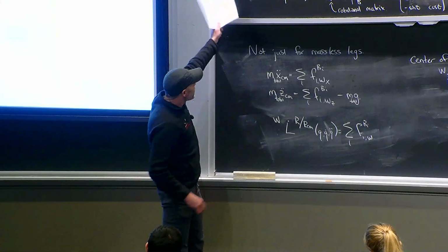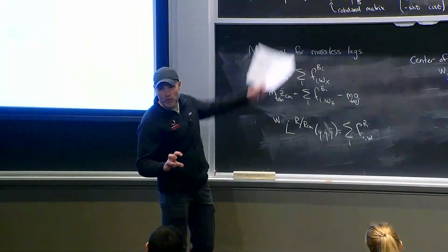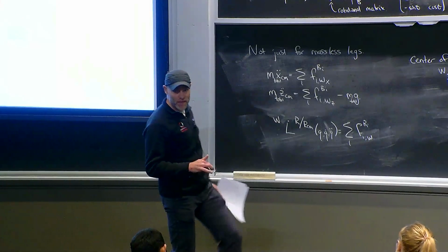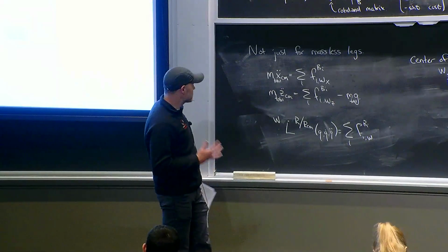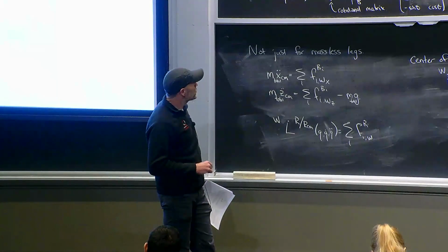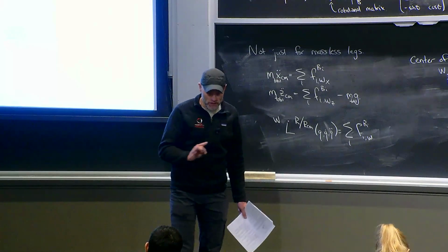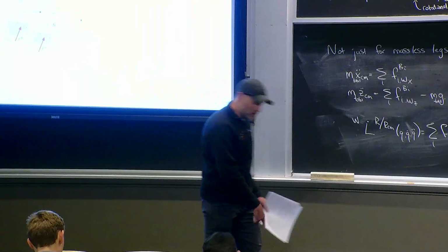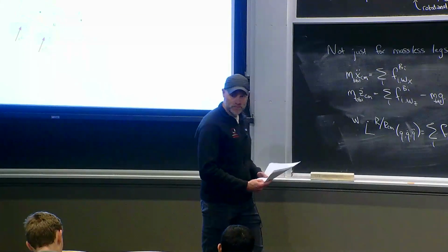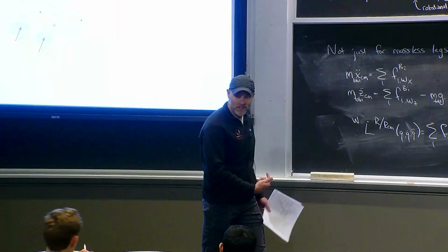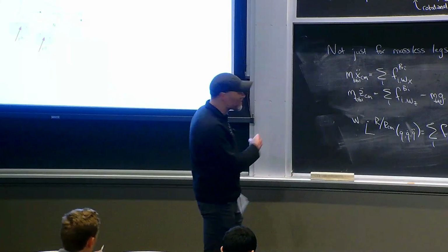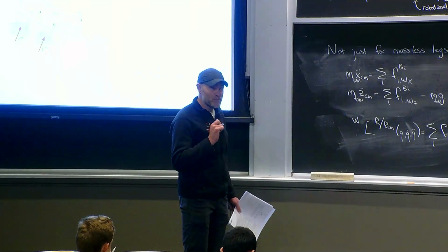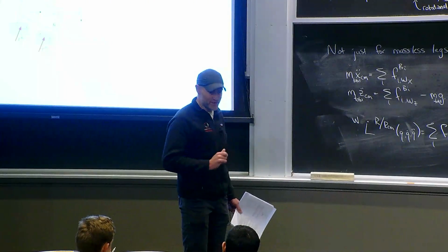Now, otherwise I have these dynamics, and I have a bunch of constraints on when F can be non-zero. When I'm touching the ground, I can push. When I'm not touching the ground, I can't push. That's the essence of the problem. There's one other thing we left out. In the walking robot, in the compass case, we talked a lot about the impulsive collisions. We said that there was energy lost every time your foot hit the ground. In the humanoid case, people mostly ignore that. That's not purely justified, but it's almost justified.